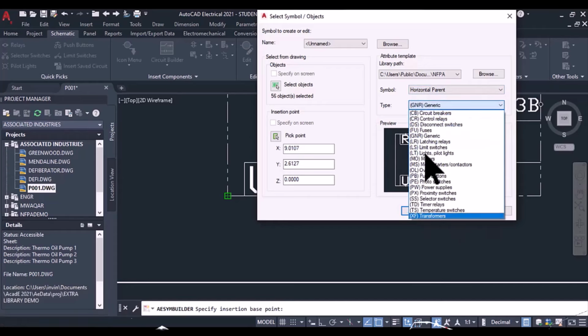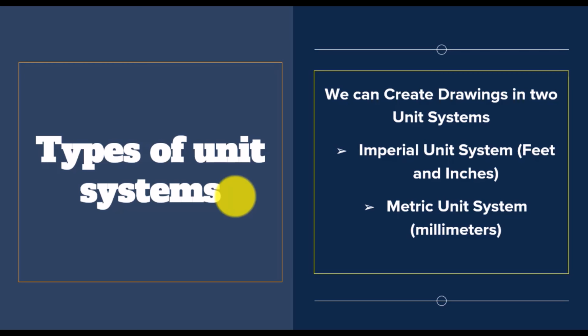Finally, let's talk standardization. This seems to underpin the integrity of the whole system. It's completely non-negotiable. Your drawings have to follow established industry standards. So in North America, that's usually ANSI. Internationally, it's often IEC. And those standards dictate everything. Everything. The look of the symbols, the way cross-referencing works, and crucially, the measurement system, metric or imperial. And you set this at the very beginning of a project. Right at the start, in the project settings menu.